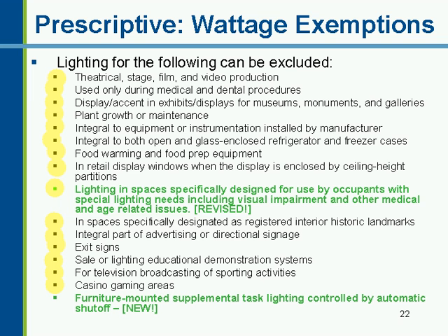Casino gaming areas. If it's a gaming area, the lighting is exempt. If it's a termed back-of-house area where there isn't casino gaming going on, those lights still have to comply, but the gaming area itself can be exempted. A new one for 2007 is if you have task lighting that's furniture mounted and it has an automatic shut-off provision, such as an occupancy sensor, it can be exempted as well.